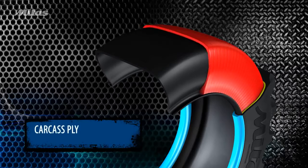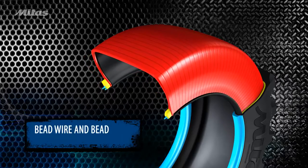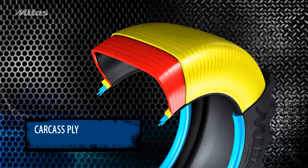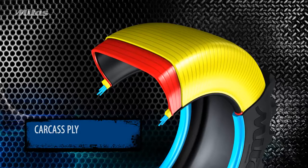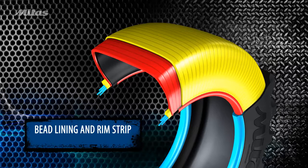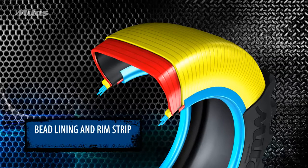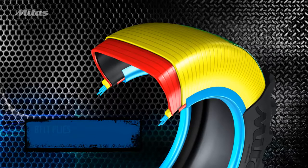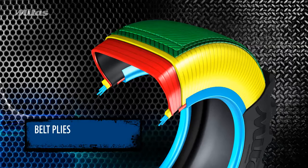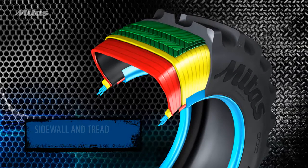This is the first carcass ply. Then the bead core and bead wire. And then another carcass ply, bead lining, and rim strip. These are belt plies. And finally, the sidewall and tread.